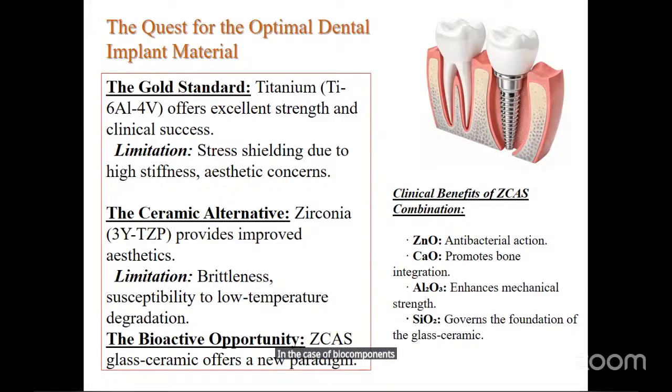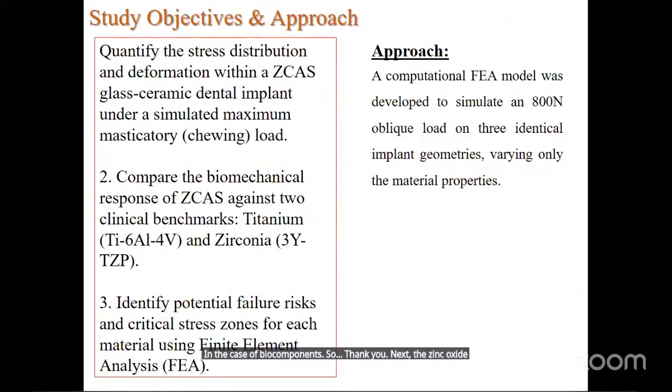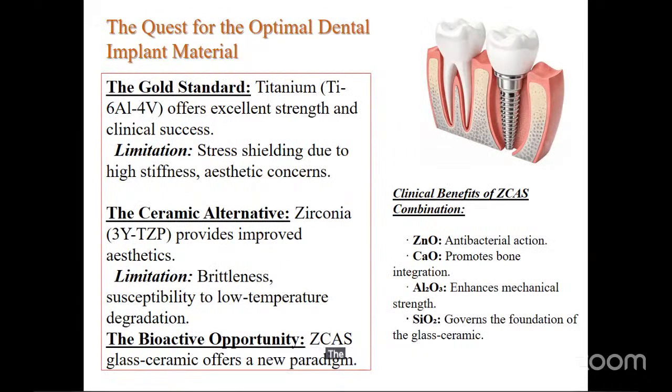The zinc oxide in the composition provides antibacterial action, based on previous literature. Calcium oxide will promote bone integration, because we all know bones are almost 90% made of calcium. Aluminium oxide will enhance the mechanical strength of the composition in general, whereas the silica oxide will be the host or glass-forming oxide.